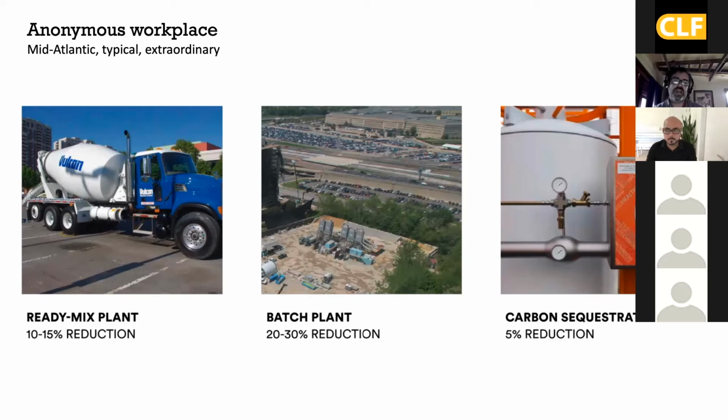And I do want to point out that CarbonCure was part of the mixes for both suppliers and achieved roughly a 5% reduction in global warming potential. That's a little bit lower, as you can see, than what we did with the specific mixes in terms of reducing cement and increasing supplementary cementitious materials like fly ash and slag. You go to the next slide.